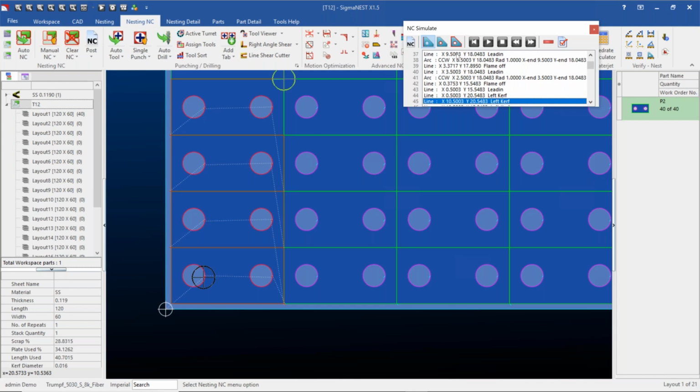This method is used for accuracy for the common cutting versus the auto slit. You can have more movement in the common cutting, releasing the stress within the material, and you can get the internal parts moving more than you want them to. So in this case here, you're maintaining the sheet stability as it's cutting along.